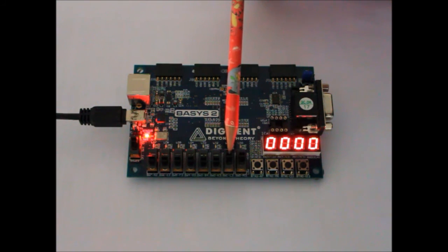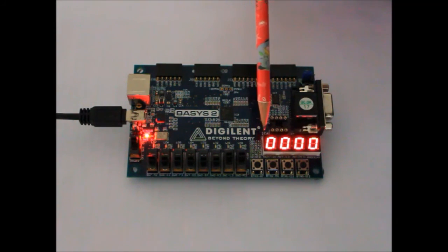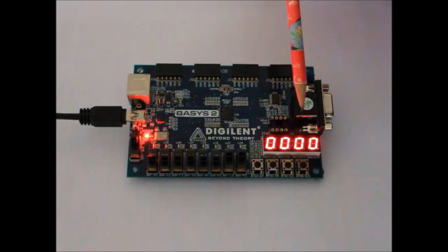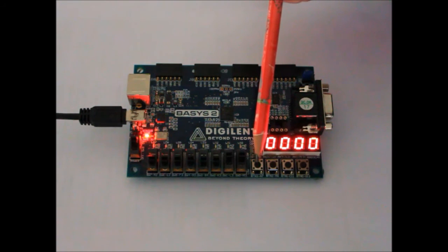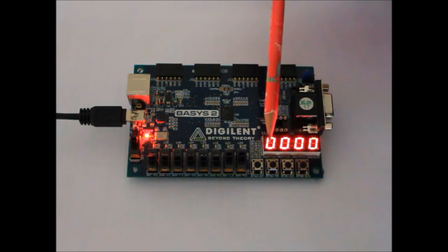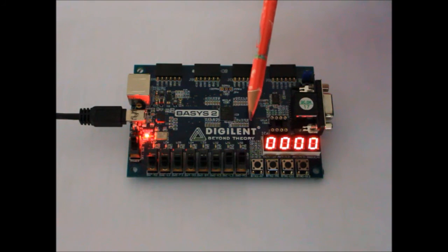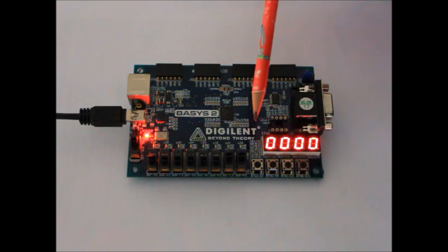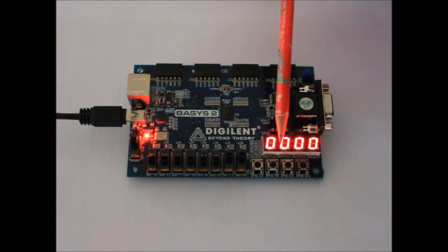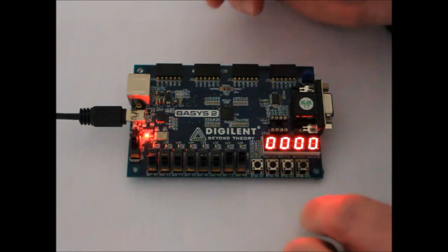And switch 1 over here is, when we put a high on it, as it is now, enabling us to freeze the count or stop the count. And that's been set up all in the software. Button 3, this button down here, allows us to reset the counter to 0. Within the programming itself, I have also manipulated one of those modules, which is the clock divider module. That's just changing the speed of the count, so you can do that by manipulating the frequency that comes in. Now we'll do a bit of a demonstration.